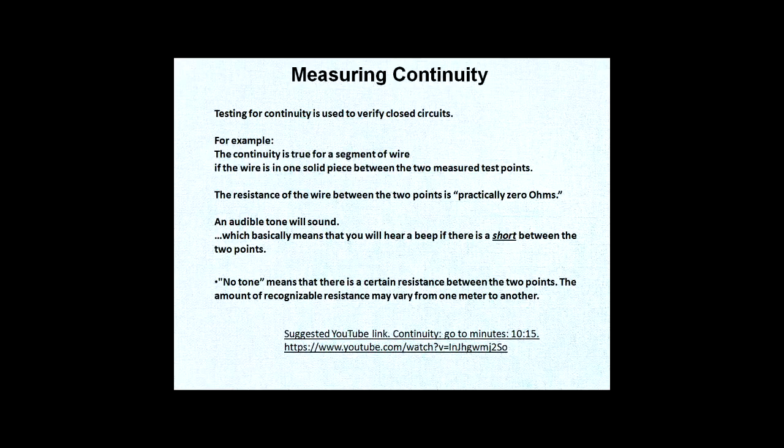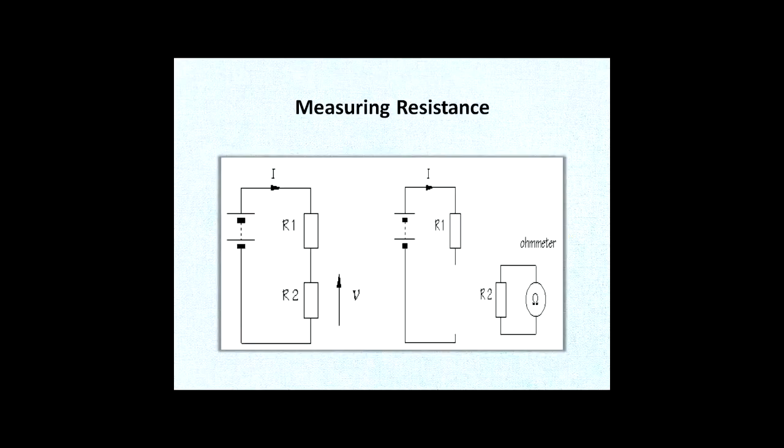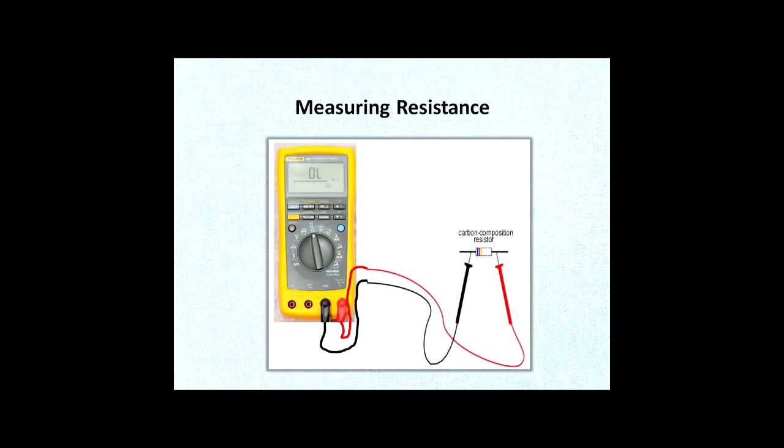Keep going. This is what I just showed you, so I'm not going to go over that. Now, this component, this resistor here is completely removed from the circuit. So first de-energize the circuit. Oh, somebody didn't de-energize the circuit here. Oh, Mr. Bach, okay. All right, this symbolizes removing the component out of the circuit and connecting an ohm meter to it. But I just went over in great detail a few seconds ago what I meant by that.